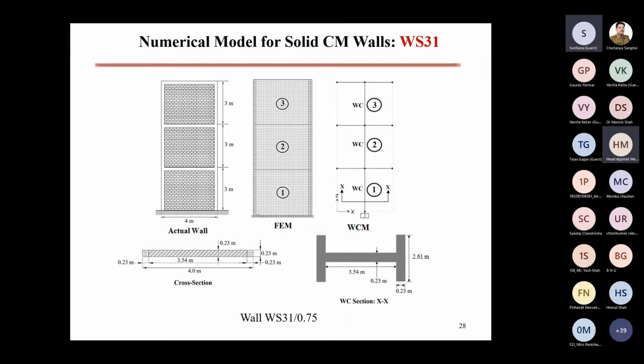In the middle, it is FEM, the finite element model, so it is all modeled as plate elements. And then the third one is WCM, the wide column model. The main purpose was to check what is the difference in the response of the finite element model and the wide column model. She was doing static analysis mostly for this and applied lateral load that would simulate the shape of earthquake loading.